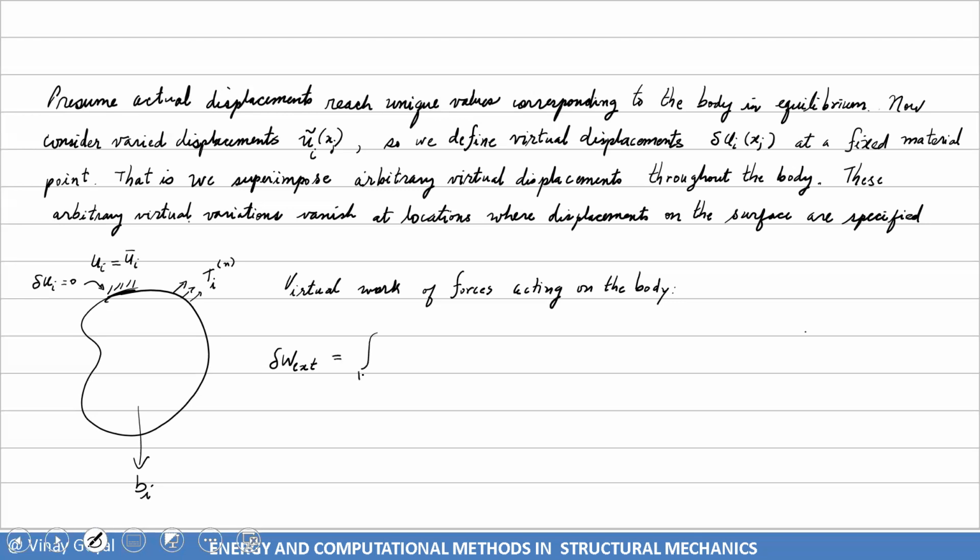I have the body force B_i, so that's the integral of B_i del u_i dV, right? Plus the integral over the surface of T_i n del u_i dS.